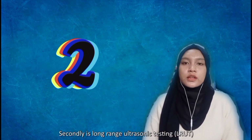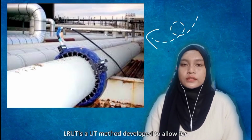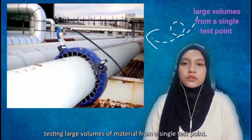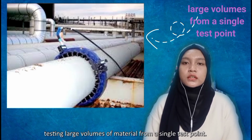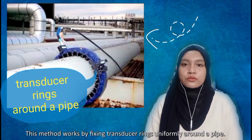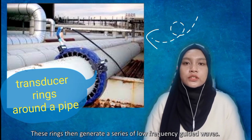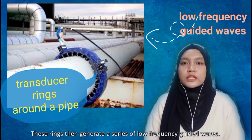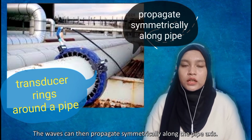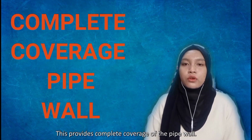Secondly is long-range ultrasonic testing, or LRUT. LRUT is an ultrasonic testing method developed to allow for testing large volumes of material from a single test point. This method works by fixing transducer rings uniformly around a pipe. These rings then generate a series of low-frequency guided waves. The wave can then propagate symmetrically along the pipe axis. This provides complete coverage of the pipe wall.